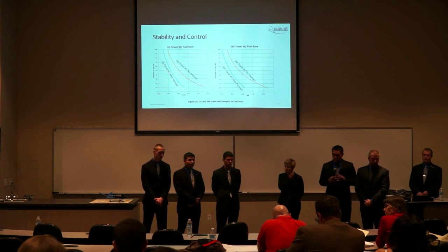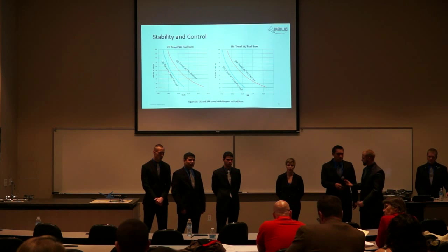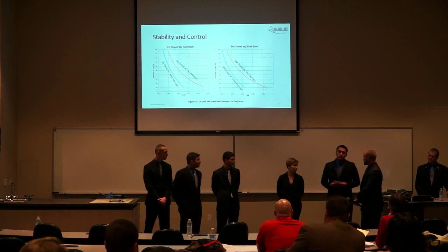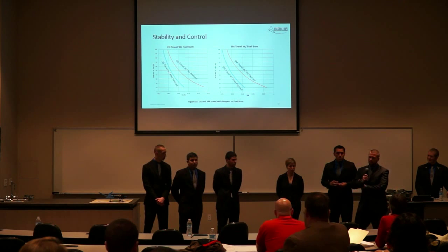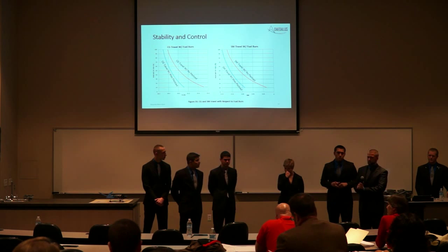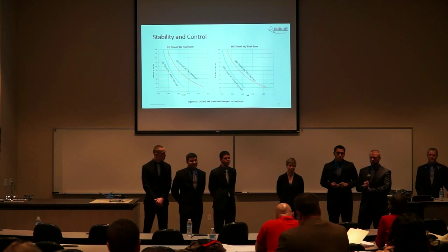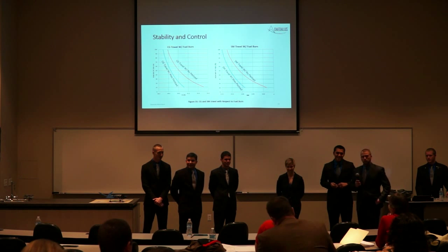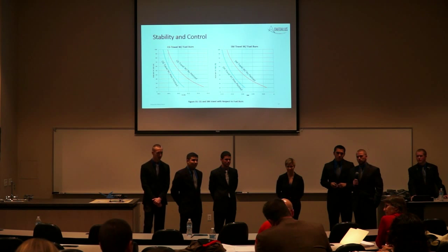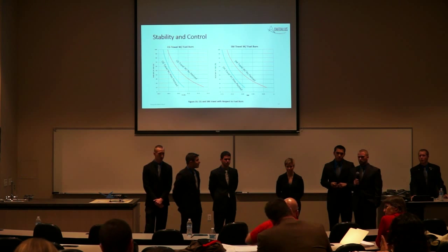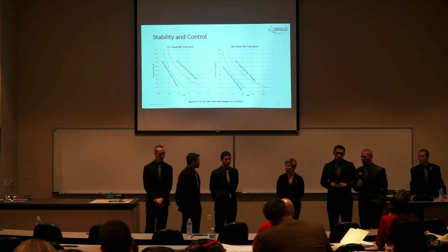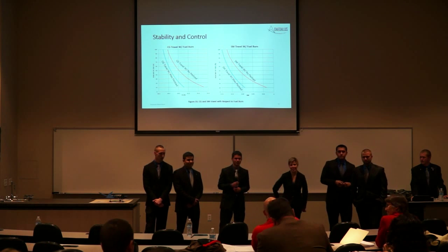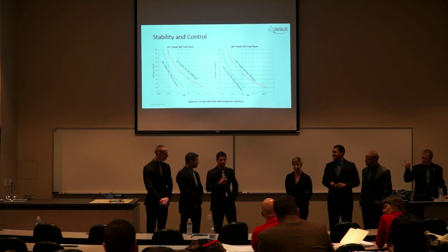Going back to some engine stuff, did you look at single engine numbers for takeoff and landing and what your minimum runway requirements would be? No. I think we assumed that if you only have one engine, you probably wouldn't want to try taking off, but if that's something typically done in industry... Say you refuse to take off and then you'd have to brake, so how long would the runway have to be? You're talking about engine failure during roll. Yeah. You power up, you go into the roll, you lose an engine. Can you take off? Or if you're going to abort, how long a runway do you need?